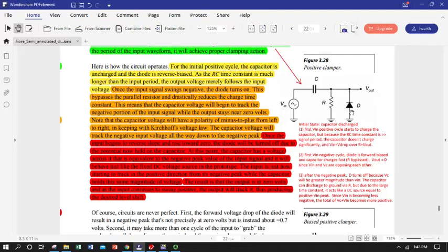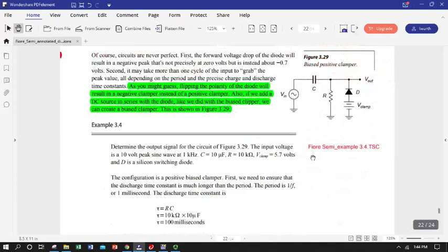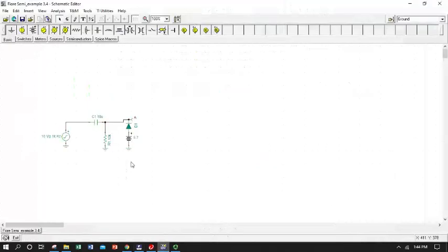And of course we can adjust that. We can make sure this diode doesn't open until we've gotten above or below V forward with its own DC offset. So we can put a little clamper DC source and change our clamping point, so it isn't just the peak. We can move it around the way we did our clippers, but basically the whole concept is we charge the capacitor to the peak of our signal, or the peak of our signal with a known offset that we put in, and not just a constant offset. So let's take a look at that in our simulator, see how it works.